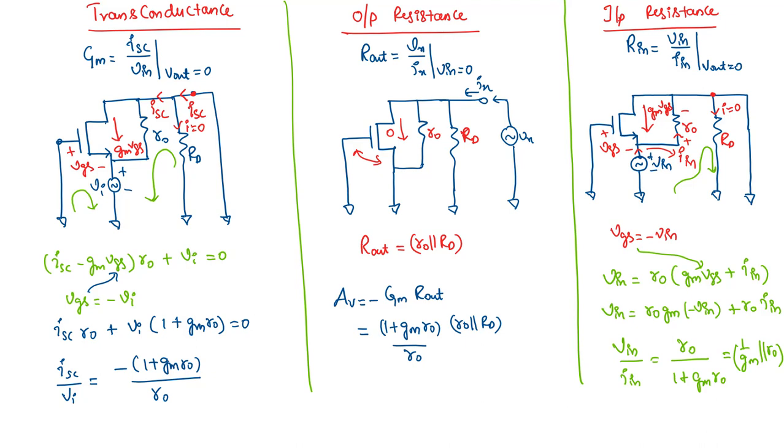So in the common gate stage the input resistance is going to be less. If you look at the overall analysis we did for the common gate stage, the gain doesn't have a minus sign, which means the output voltage is not going to have a 180-degree phase shift compared to the input. And coming to the input resistance, for common drain and common source stages, we always had very high input resistance, and we said it's infinite because we see gate to source terminals at the input. But in this case, the input resistance is finite as we are driving the input signal through the source terminal.